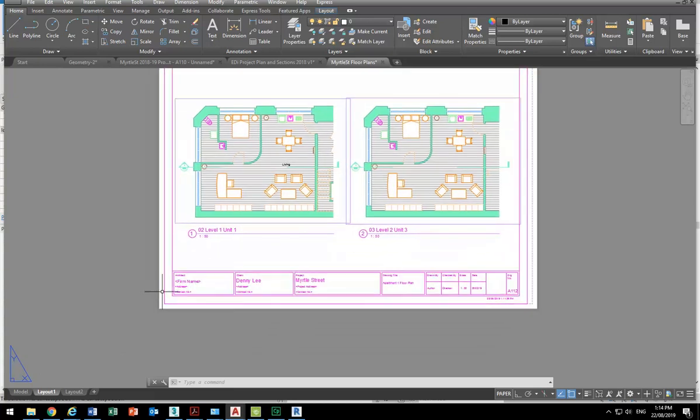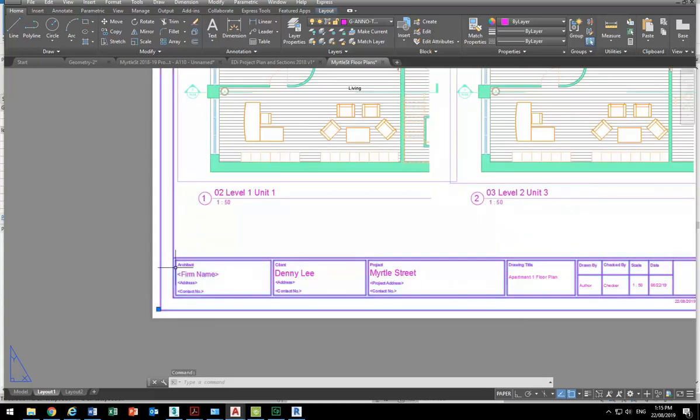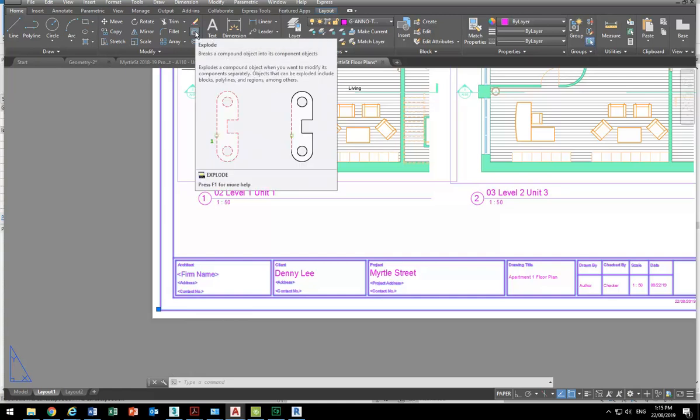And then once you've got this title block, just remember anything that's grouped like this, it doesn't matter whether it's grouped as a block or a polyline, you can always use the same command to break it apart called explode. And this is another great thing about AutoCAD that Revit doesn't have. You can explode anything. So explode breaks anything apart. It breaks anything down to its smallest component, essentially. So explode, great option. Wish they would just put it in Revit, but they never will. Because of the way Revit's designed, for some people it wouldn't make sense to have explode, but I think they should still put it in, but anyhow, they won't. So anyhow, it's great. You can always go back to AutoCAD and then explode anything.